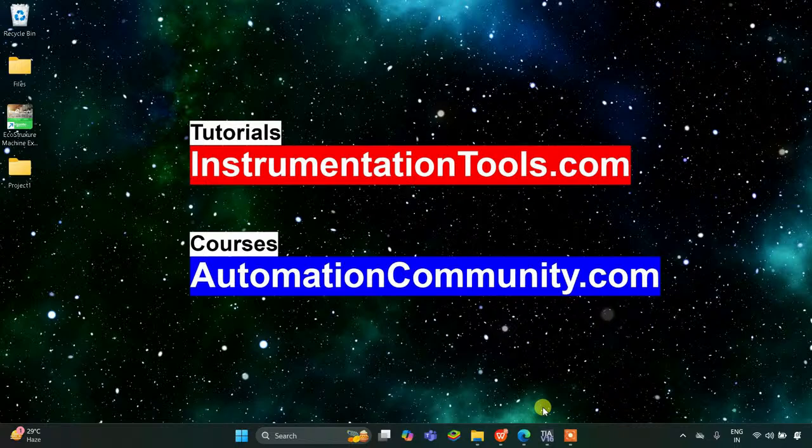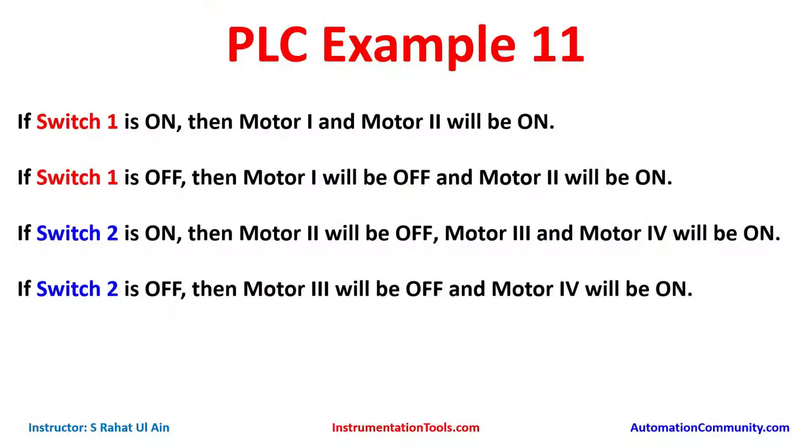Today in this video, we are going to discuss an example in which we will use normally open contacts, and we will also be using set and reset coils. So let's start. Example 11. If switch 1 is on, then motor 1 and motor 2 will be on. If switch 1 is off, then motor 1 will be off and motor 2 will be on. If switch 2 is on, then motor 2 will be off, and motor 3 and motor 4 will be on. If switch 2 is off, then motor 3 will be off and motor 4 will be on.